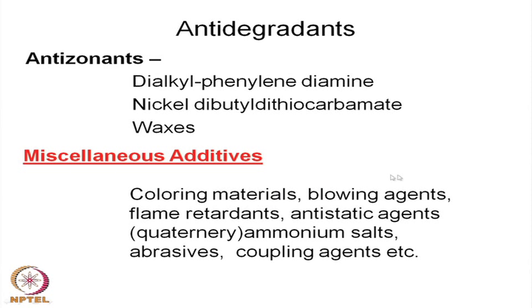Sometimes cellular rubber products are used, rubber sponge or soft rubber, say cellular rubber products, which can be open cell sponge or closed cell sponge. These are made by using some blowing agents. The blowing agents can be either a gas or some gas generating chemical compound.